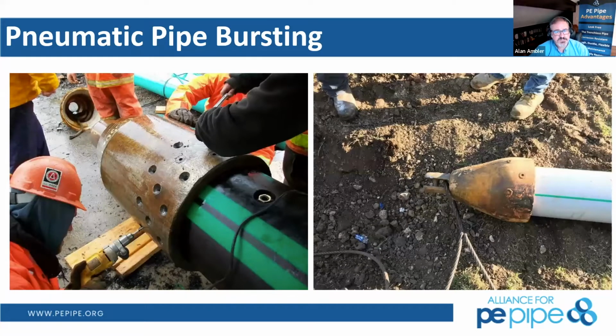In some instances, high-density polyethylene makes it very convenient to attach these expander heads directly to that HDPE. So what you're seeing here is an expander head that's simply drilled into the HDPE. And that drill, as we come through, that screw holds onto it, and that's more than enough to keep that expander head on that high-density polyethylene. Then that piece is cut off before we're put into place.